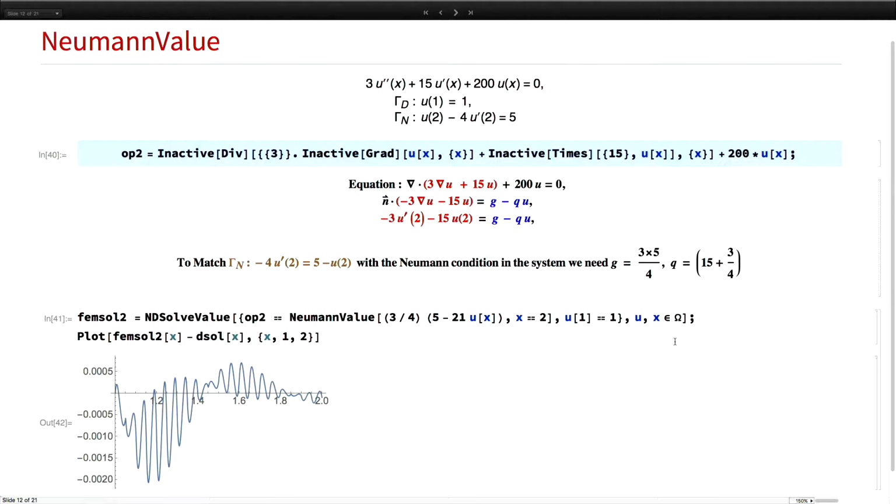Okay? So there is significant flexibility inside of the FEM framework in that you can manipulate these equations in any shape or form, but when you're dealing with Neumann conditions, it's important to know what form you gave it in so that you can apply the right boundary conditions.